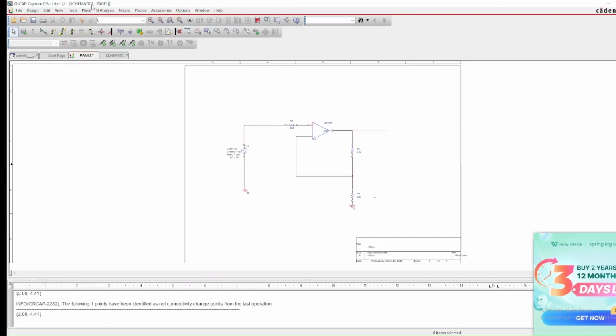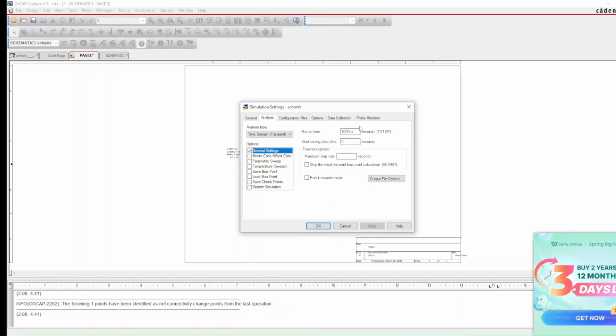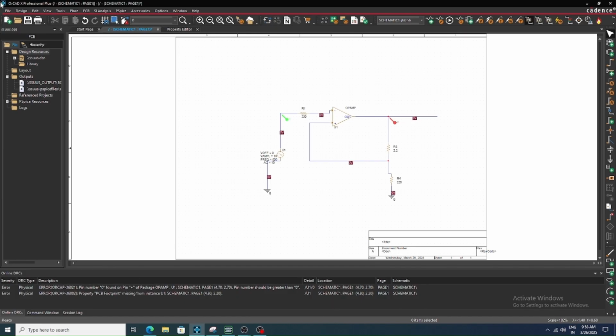Click on run. Before clicking it, you need to check whether the simulation profile has been set. Here you can see PSpice. Clicking it, a pop-up comes up, and you can give it a name. And after that, let's click on PSpice simulation. Give it a value here, runtime. I'm going to give it 100 milliseconds here, and the circuit is basically done.